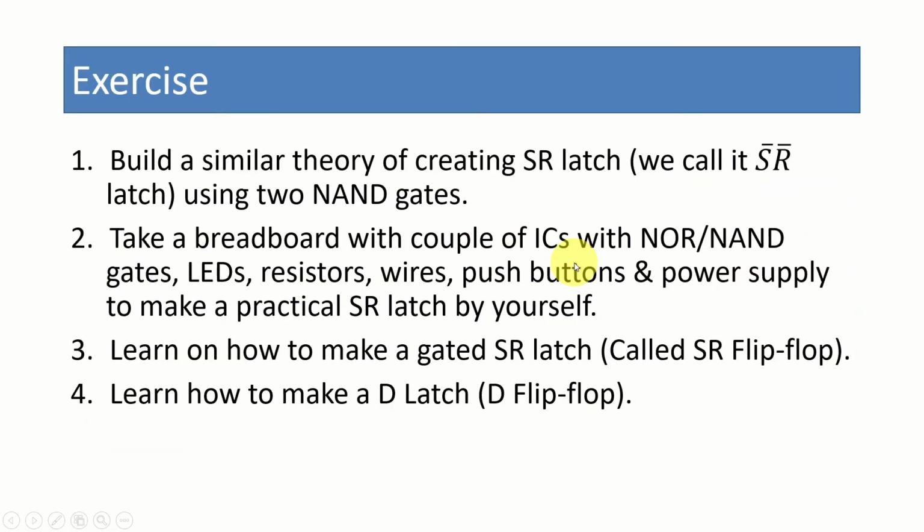So I hope you have understood the SR latch perfectly, and this is a good time to think about the next steps. There's another latch called S bar R bar latch, which is made using two NAND gates rather than using two NOR gates. The circuit is exactly the same, other than you replace your NOR gates with NAND gates.